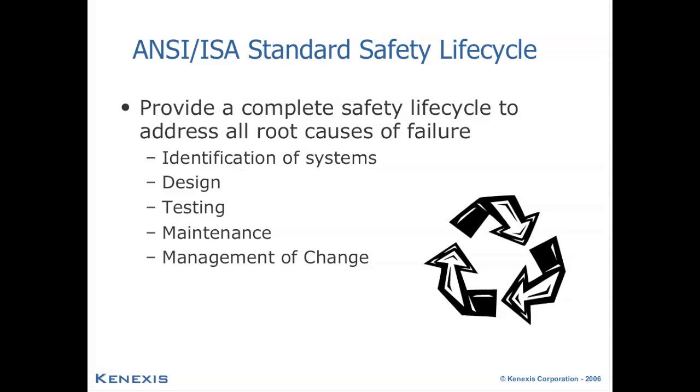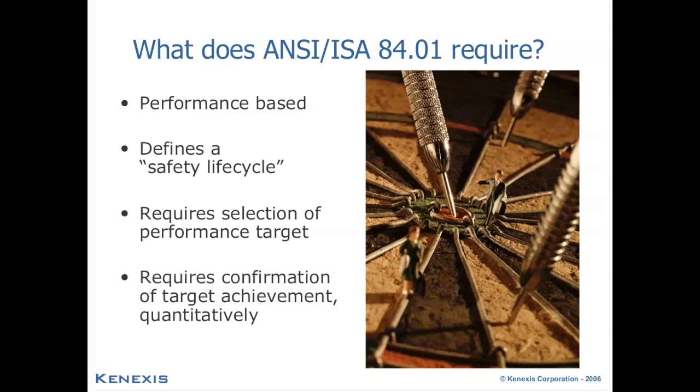The safety lifecycle approach was included in the original S84 standard that was promulgated back in 1996 and has been broadly updated and added upon using the International Electrotechnical Commission, or IEC's, 61511 standard that has been harmonized with S84 and promulgated in the latest 2004 version of the standard.